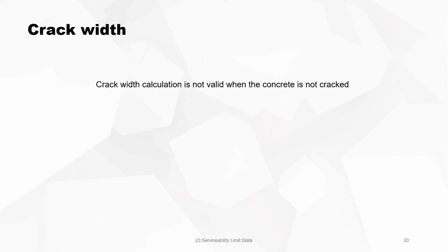Crack width calculation is not valid when the concrete is not cracked. Don't forget that. Every time you do a crack width calculation, you must check that the applied bending moment is bigger than the cracking bending moment. Otherwise, all formulations are wrong.